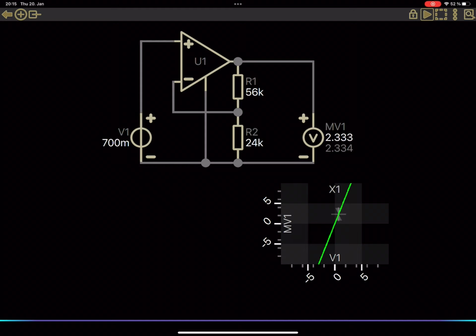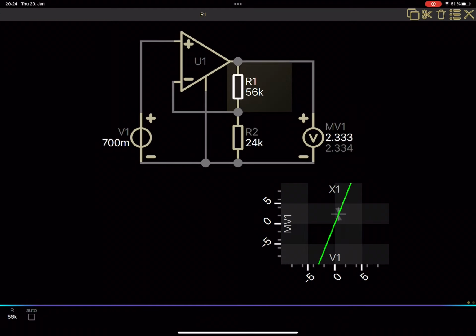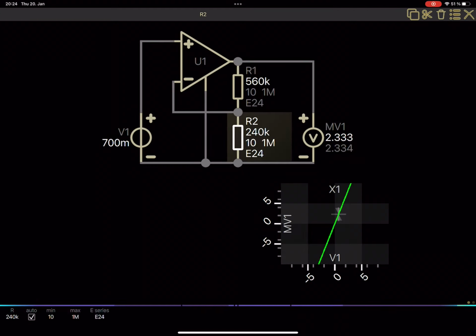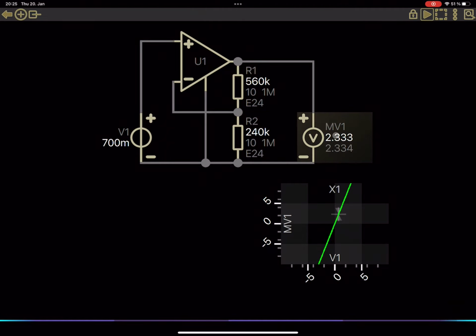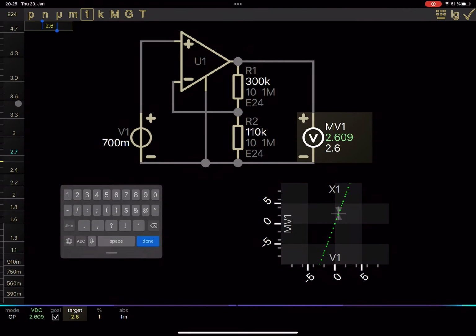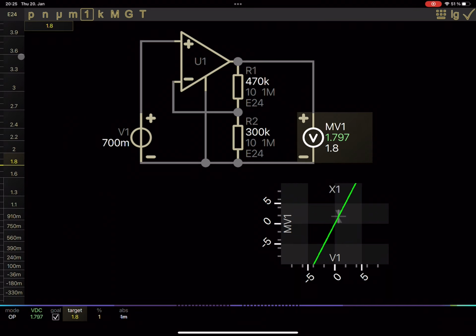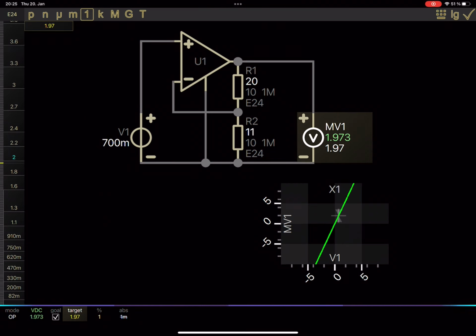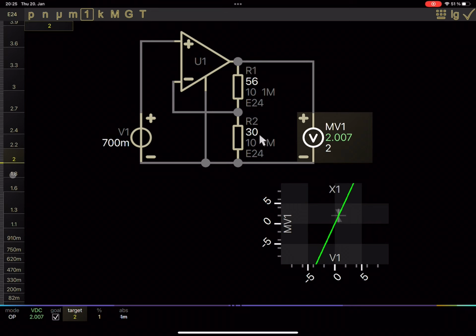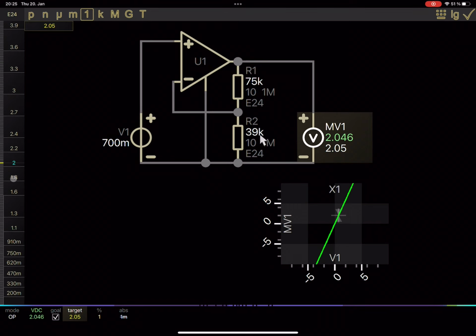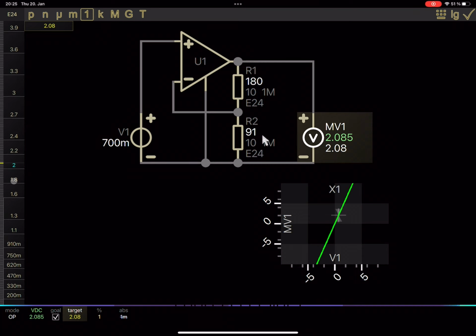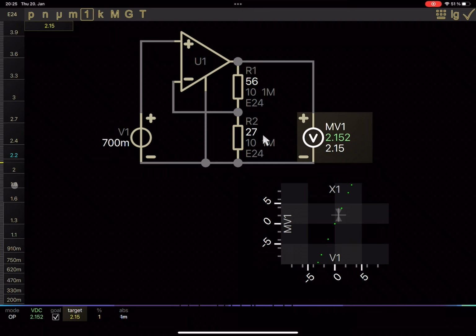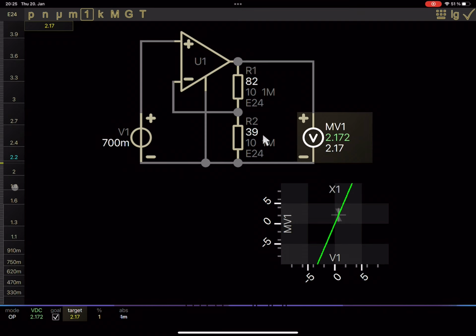Of course, as with the voltage divider in the preceding video, we can simply fulfill arbitrary design targets by utilizing CircuitShepherd's parameter optimization feature. While the inner resistance of the previous voltage divider was well defined due to the target value of the ohmmeter, the operational amplifier circuit is a little under-constrained here. An indication for missing constraints may be heavily changing auto values due to only minimal changes of design targets.